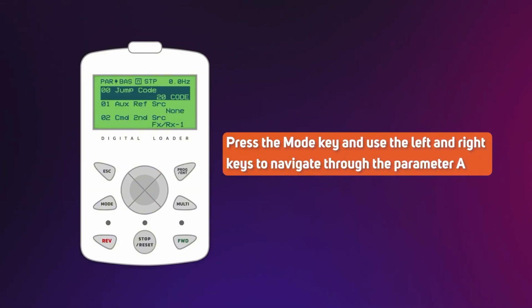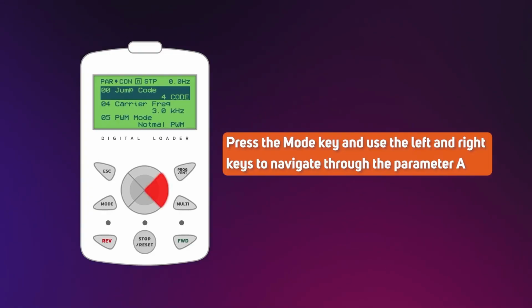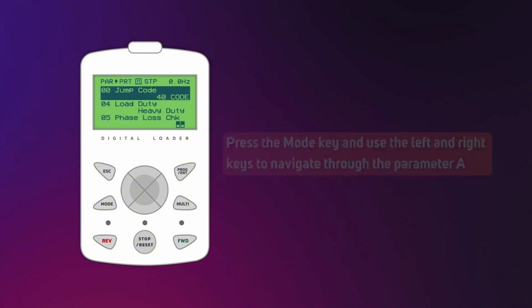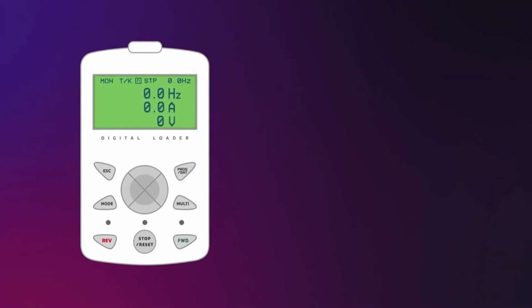Now I want to go from the base group to the next group. I press the right button again and enter the parameter group ADV, or Advanced. In the same way, by pressing the right button, we move between parameter groups and can go from one group to another. For example, we want to go to the DRV group and set the DRV01 parameter to 30.